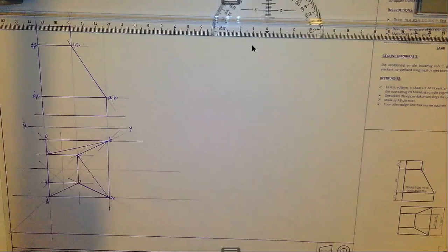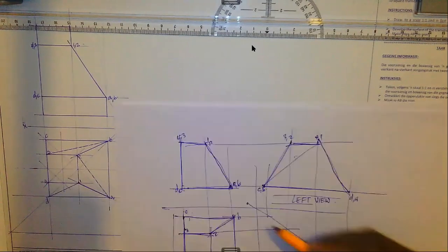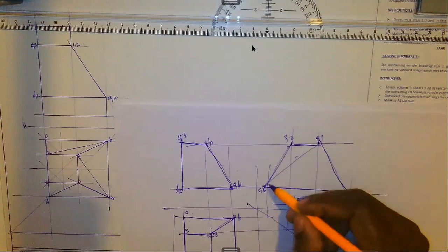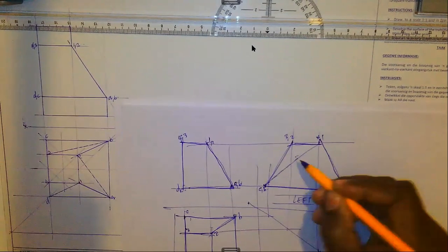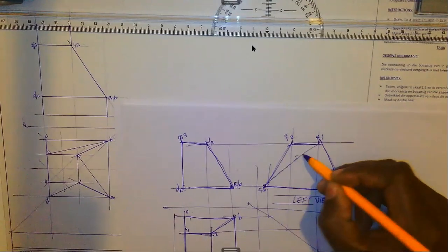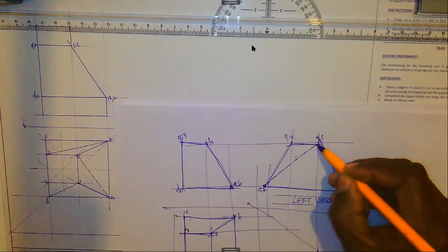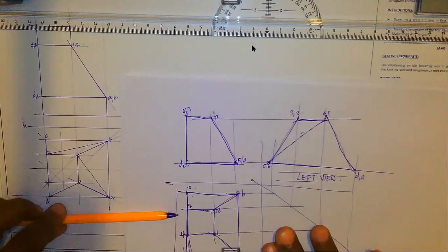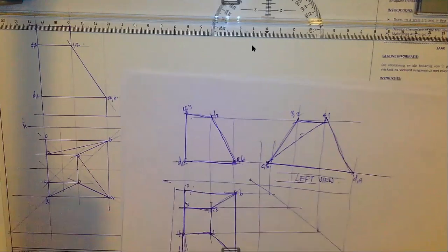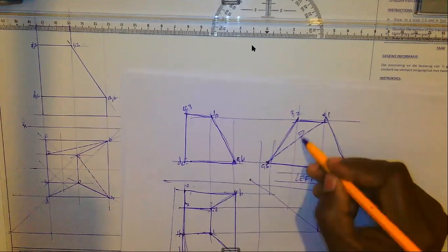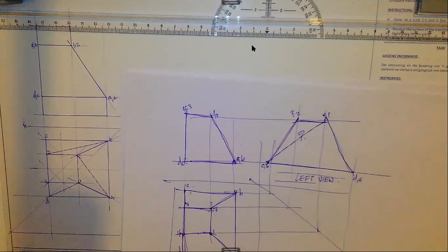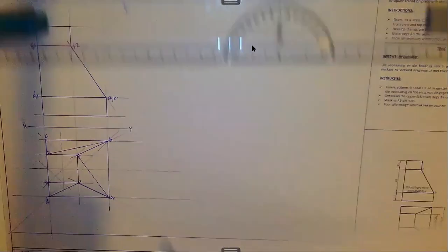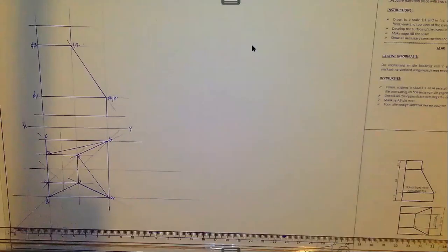Remember what I explained? If we are looking at this one as well, we have got a specific line which is being connected from C to point number 4, as you are looking from the left-hand side. So there is a line which is different to the outline that we have. So we would also require to have a true length of that line. The next thing that you would want to do is to establish the true lengths, okay?